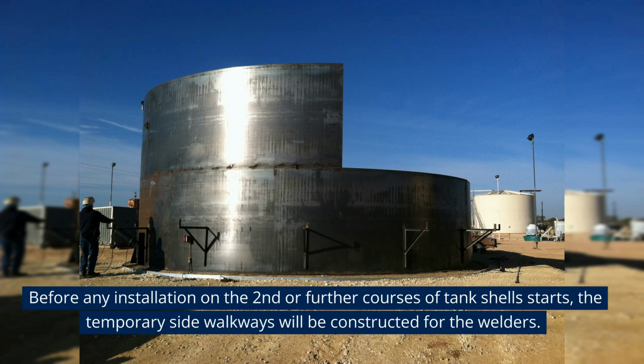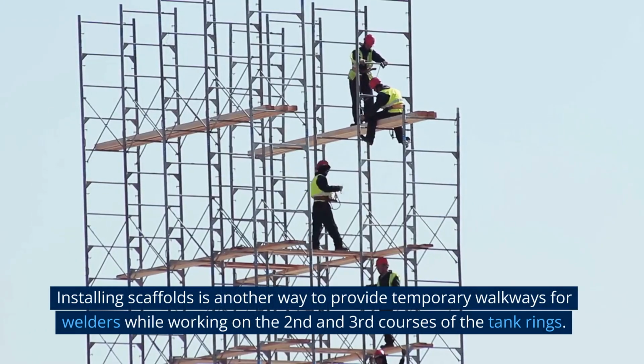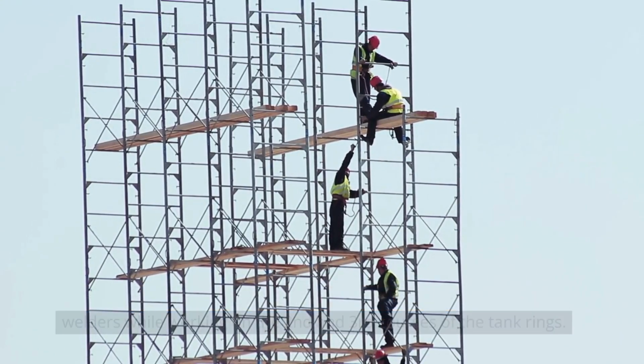Before any installation on the second or further courses of tank shells starts, the temporary side walkways will be constructed for the welders. Installing scaffolds is another way to provide temporary walkways for welders while working on the second and third courses of the tank rings.